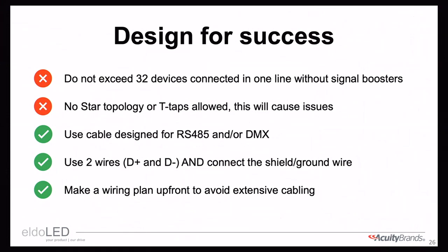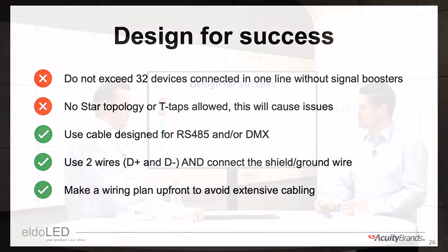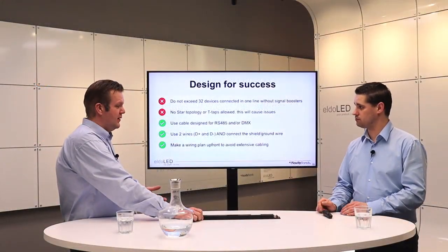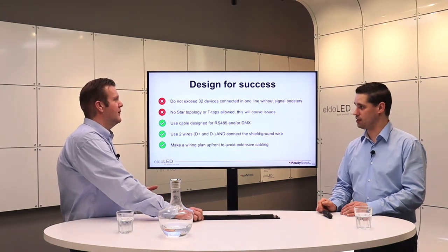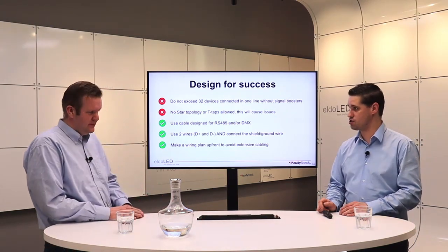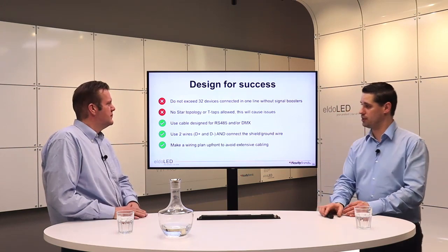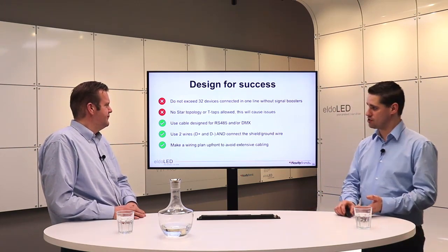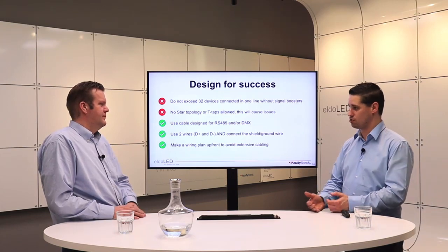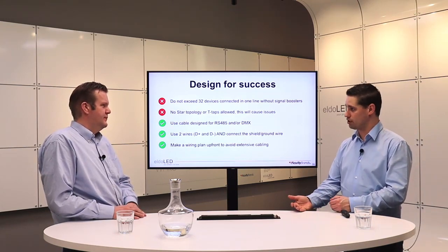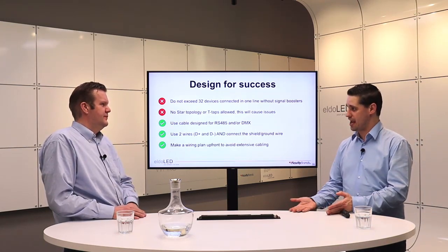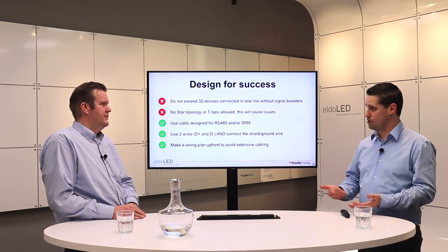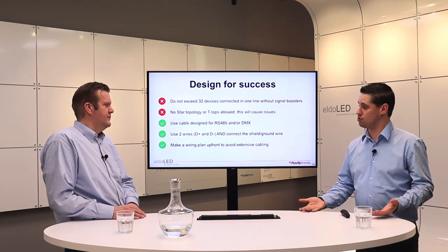Then there's another question. So a 4-channel driver is one device. Yeah. And if you have a 1-channel driver, it's also one device. Exactly. Okay. So it's every physical device connected to the cable, indeed. And that may not exceed 32. And yes, for sure, if you connect 33 or 34, it will still work, but you're out of spec of that standard. And that will, in the end, give you trouble if there are too many external influences on that DMX line.